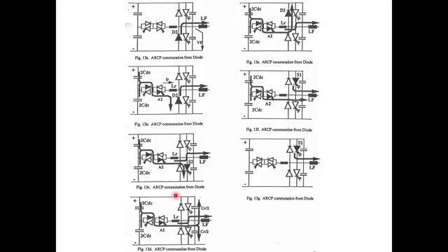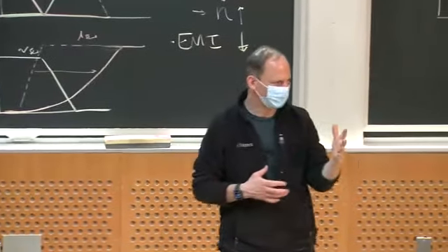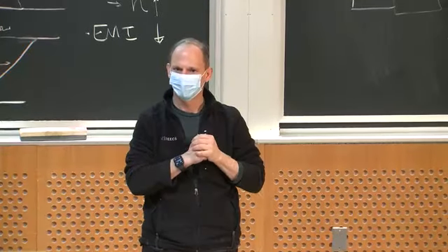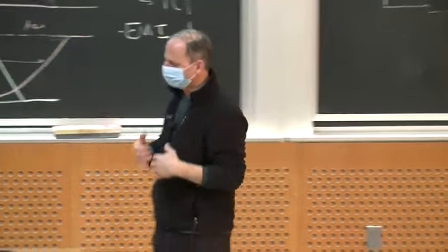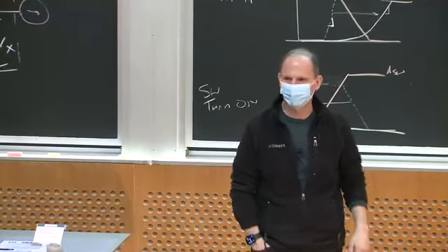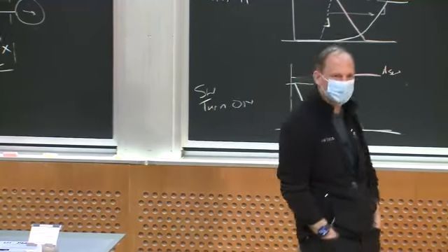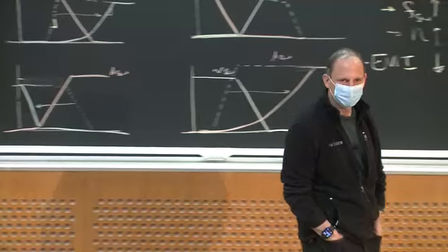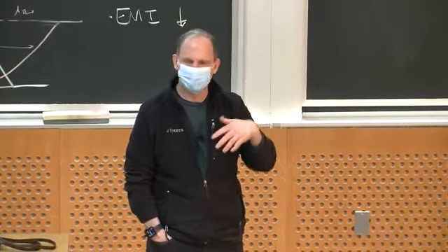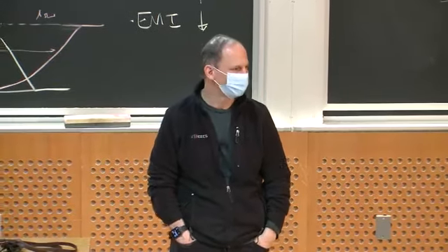And if you think of every other possible switching transition and direction of the load current, you can find a sequence that will let you use the auxiliary circuit to make that transition for you. And so this is a complicated circuit, relatively speaking, especially when he did this in the late 80s, early 90s, as controls and sensing and everything was really complicated. On the other hand, at high powers, you don't really mind. Compared to the previous inverter I showed you, the control for that has a lot of stuff, but it's pretty simple. You just got to sense current and make your switching decisions based on commanded currents.